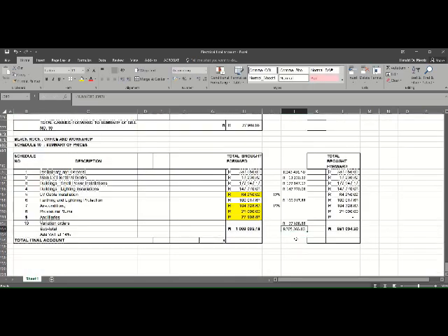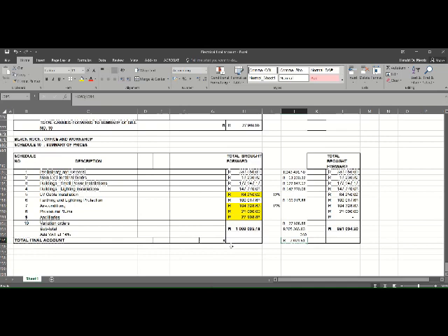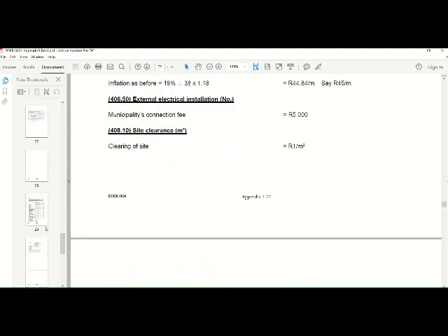Okay, so we get to our new rate, and for this building it was more or less 100, and it's two buildings of 117, or 70 times 2, so we had a construction rate of 2,000 Rand per square meter. So if you have your elemental estimate, what would happen is you would take this rate to use in your elemental estimate.